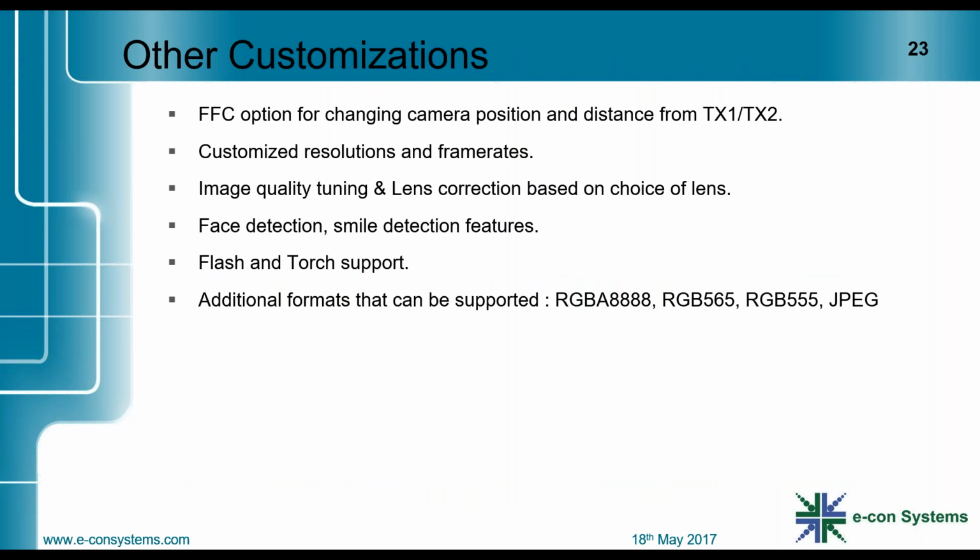So we also provide other customizations for the TX1 or TX2 cameras. We can re-engineer the hardware to support flexible flat cables, which enables the camera to be used at a distance from the SoC, which you already saw for the 6 camera application. We can also provide driver customization to change the list of supported resolutions and frame rates. We can also provide additional image quality tuning based on the choice of lens that the customer has selected. And one another unique feature in this camera is the support for face detection and smile detection. So if the customer requires that, we can support that too.